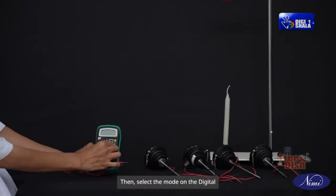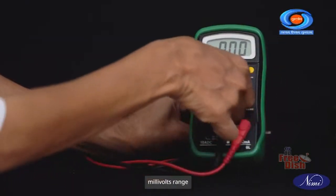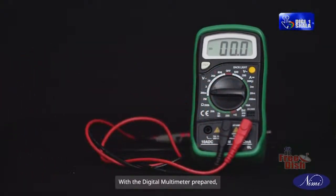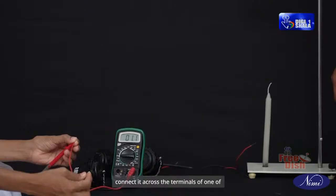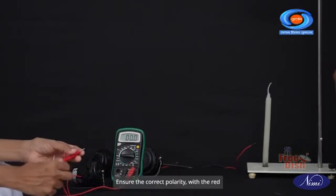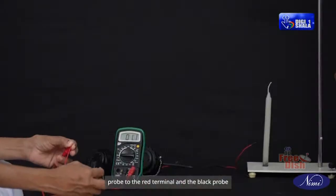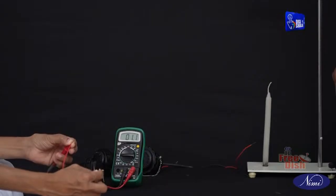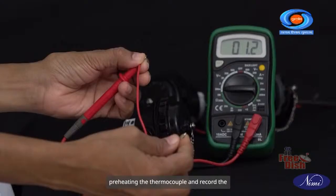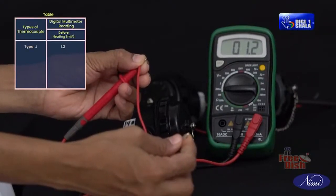Then select the mode on the digital multimeter to display in the low DC millivolts range. With the digital multimeter prepared, connect it across the terminals of one of the type J thermocouple. Ensure correct polarity with the red probe to the red terminal and the black probe to the white terminal. Measure the DC millivolts reading before preheating the thermocouple and record the value in the designated table.